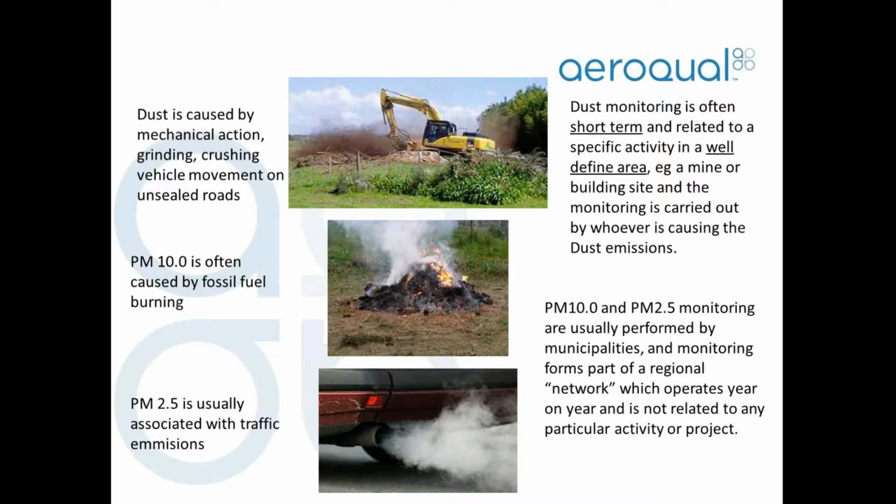And the dust monitoring is often carried out by whoever is actually causing the dust emissions. Remember again that dust is not regulated nationally. PM10 and PM2.5, on the other hand, because of the health risks, are often monitored by local government, municipalities. PM10 and PM2.5 monitoring often forms part of a regional network of monitoring apparatus which operates year on year, but is not related to any particular activity or project.